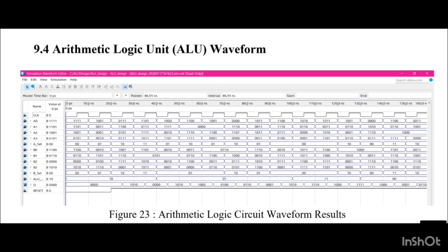The register is equipped with an active low clear feature. So when the reset input equals 0, the output is immediately cleared to 0, 0, 0, 0. So that's all from us.